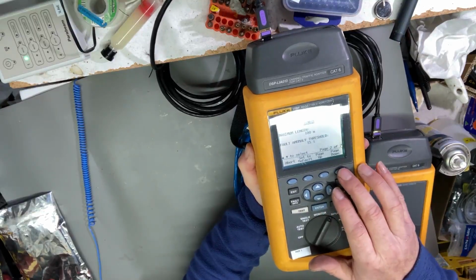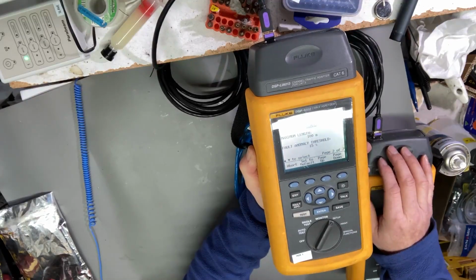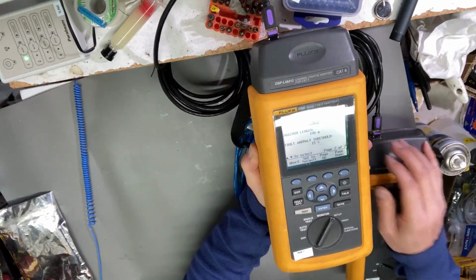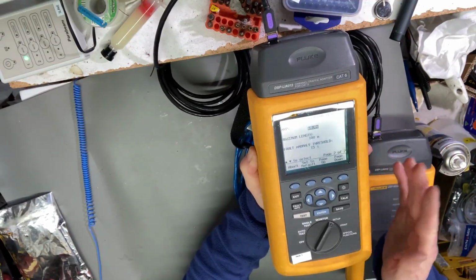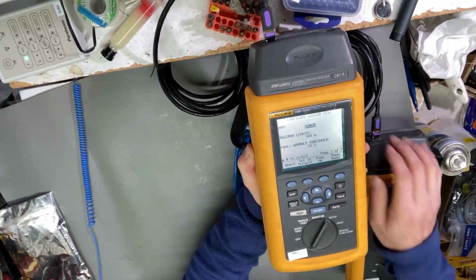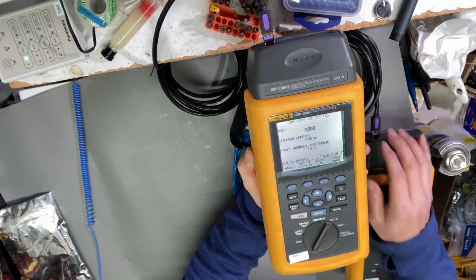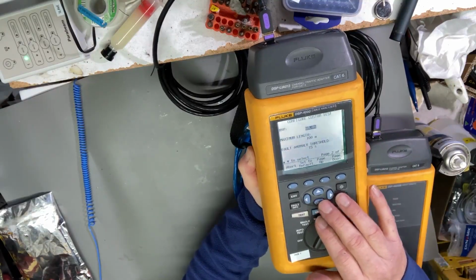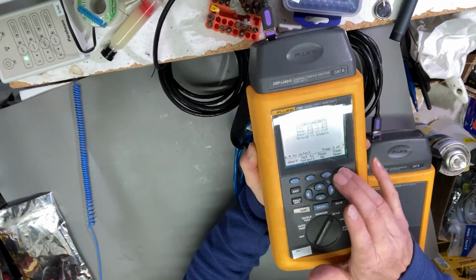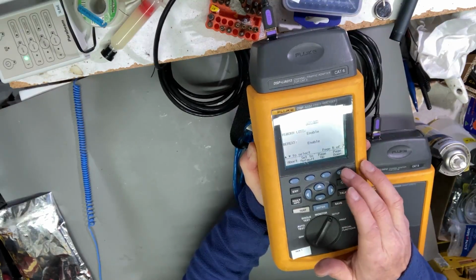Other things that you can change there, NVP, that's the propagation velocity, so that is going to change the measured length. So what you do is you'd alter that until you get a bit of test cable, and then alter that amount until that length corresponded with the measured amount that you had, and then when you tested from there you'd have a more accurate result. Typically that's going to change a little bit with cable type, but it will also change a bit with temperature, for example. Defining your anomaly threshold, different wire maps if you don't need that. Resistance, no, okay, we don't have that. Cool.